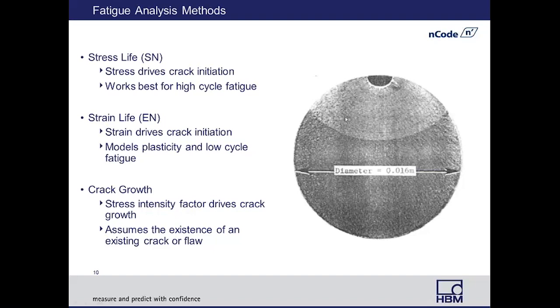And what this is showing us is actually a cross-section right through where a very common test specimen has failed. And what you can see, this is actually a specimen, if you haven't seen these before, is a necked cylindrical test specimen. Fairly small in size. It has a crack initiation that's occurred at the top, and once that crack initiation gets to a sufficient size,